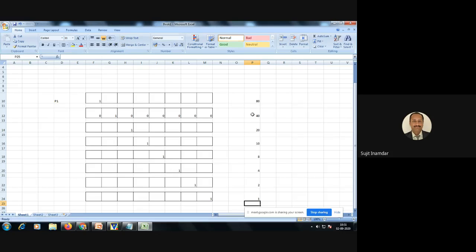So the another solution is that whatever Aboli has put over here, use only one command that is called RR. But this RR command is normally applicable for the accumulator. It works on the accumulator. So we have to take the accumulator here in between our port and the output.